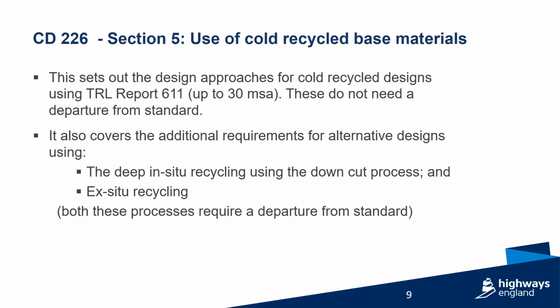Section 5. Use of cold recycled base materials. The first part of this section sets out the design approaches for cold recycled designs using TRL report 611 and is intended only for pavements carrying up to 30 million standard axles. Designs using TRL 611 do not need a departure from standard.